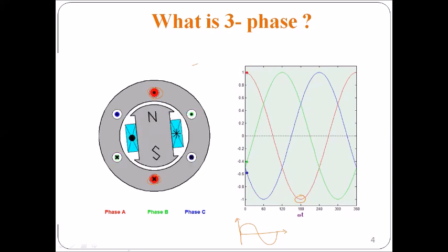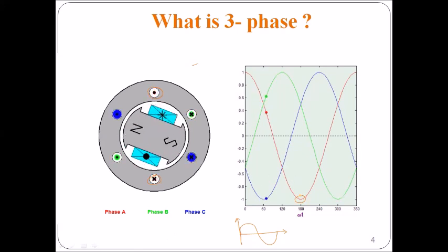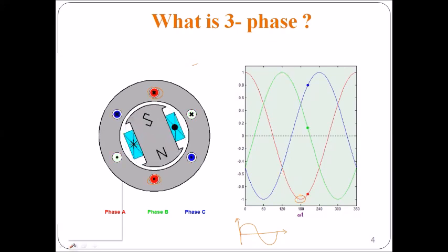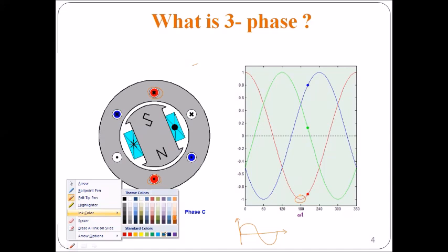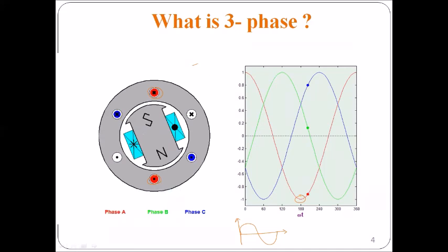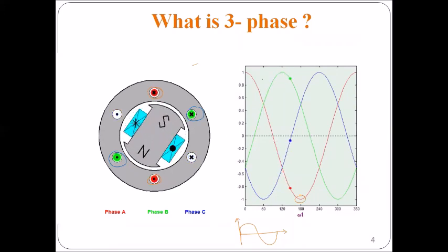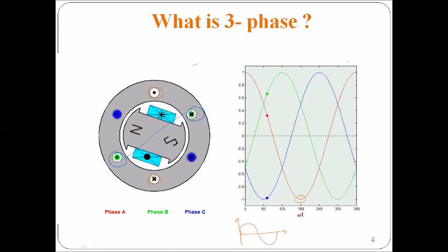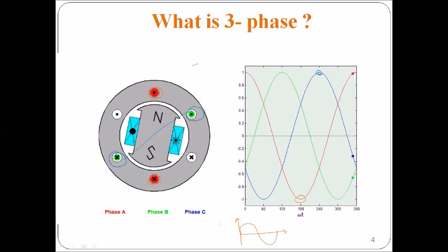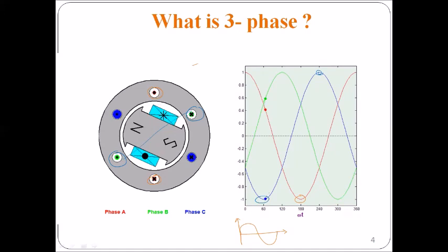So at this instant, we can easily identify that the coincidence between north and south pole is maximum. Similarly, let us take this example. Whenever it continuously rotates, we can say that the power will be maximum whenever this north pole and south pole is exactly in alignment with the conductors. So that's what we can mark as the maximum voltage which can develop.